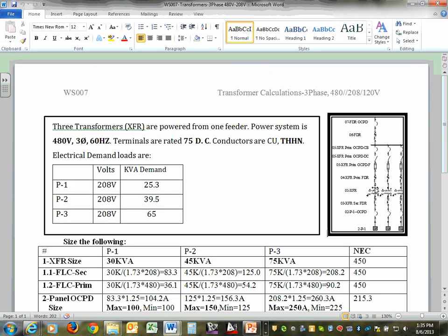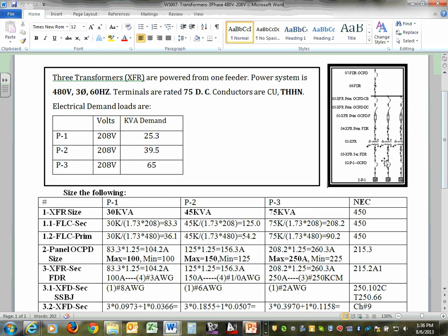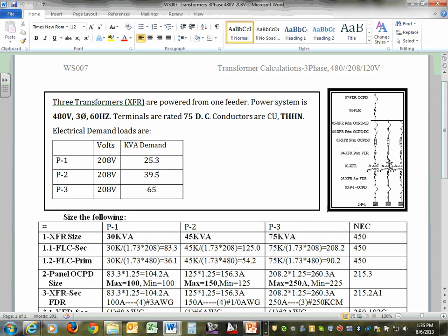So that's to protect this feeder, and then there's three of them. They're grouped together in a panel or in a feeder, and they're fed by another feeder that feeds the whole three transformer system. Does that make sense? So the voltage on this level here is 480. The voltage on this level here is 208. So basically three transformers, 480 on the primary, 208 on the secondary, feeding panels for receptacles, typically receptacles. They're grouped together and they're fed through an MCC. Any comments, guys, about the layout?